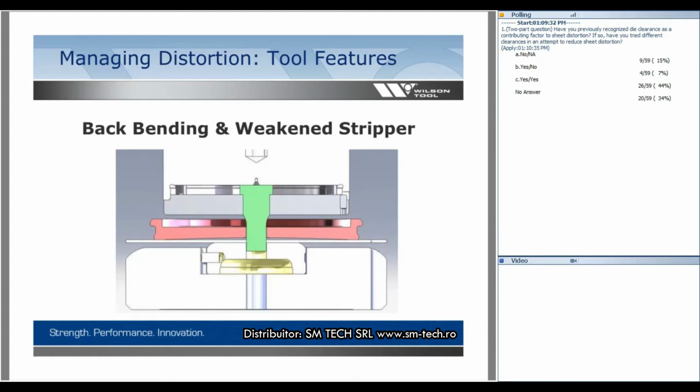Backbending, or a weakened stripper to help promote backbending. Here's a case where we used a smaller die. We adapted it to a large system. So there was this natural pivot on the corner of the die because it's raised up higher. And if we create a weaker stripper, we can create some bowing, because when you're piercing, it's usually a cup. So if I can push it in the opposite direction before I pierce it, we're trying to negate it.